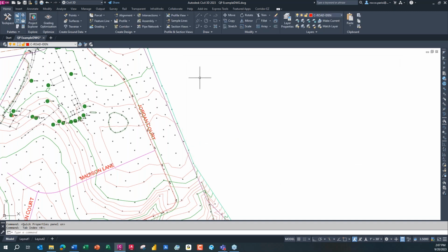And now I'm going to just start picking on a few of these items. You kind of saw it a little bit because I did have it on. But you see, I'm working with a very basic Civil 3D drawing here. I've got a basic alignment. I've got a feature line floating here. I've got some COGO points, and obviously I've got a surface running, a TIN surface. So nothing that's out of the usual stuff we use every day, but we can really make getting information and even editing and changing display styles and items like that much, much simpler with the quick properties box.